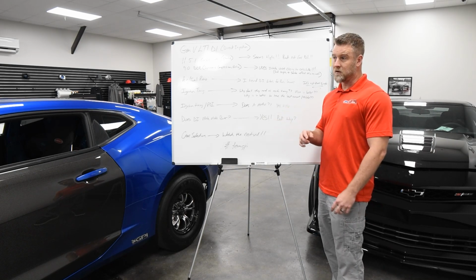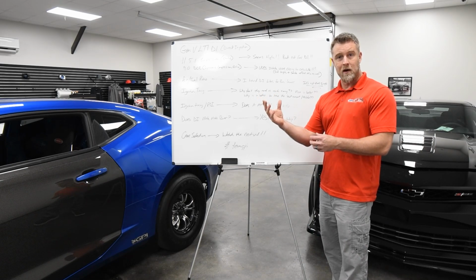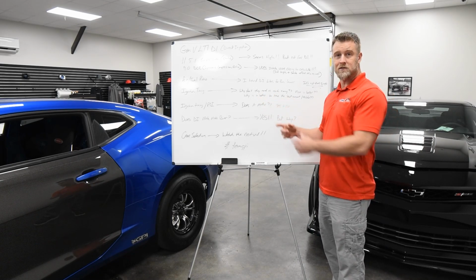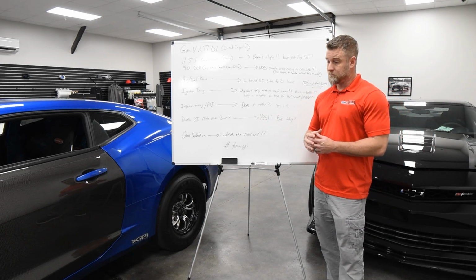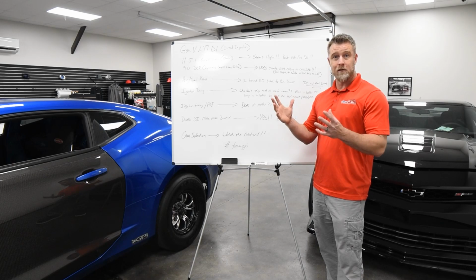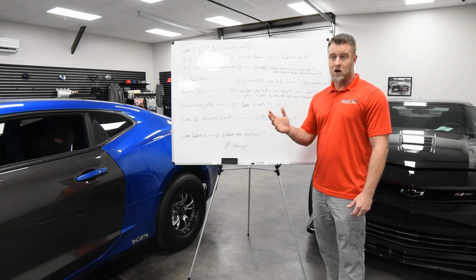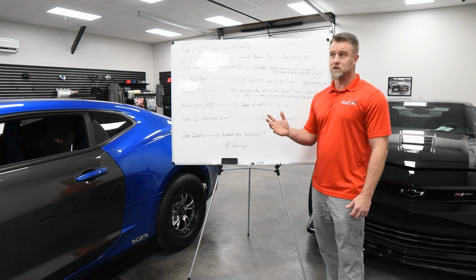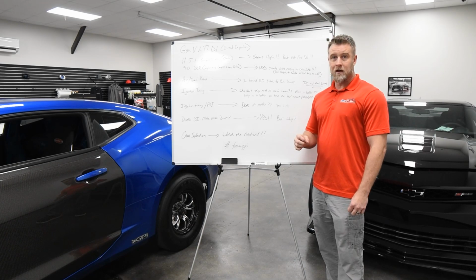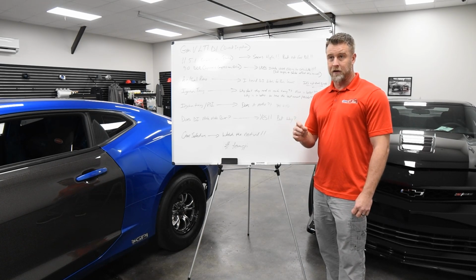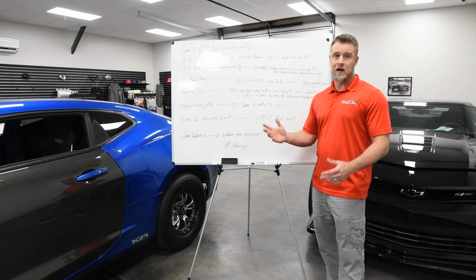Also consider that when you're putting methanol up front before the throttle body, and you're not doing it directly in each cylinder, you don't know where all that's going. I mean, most of it's obviously evaporating before it gets there, but distribution may not always be perfect with all of the manifolds. So running that thing a little richer may not show you the best power on the dyno, but it would be a better starting point until you can actually get out and see what you've got.